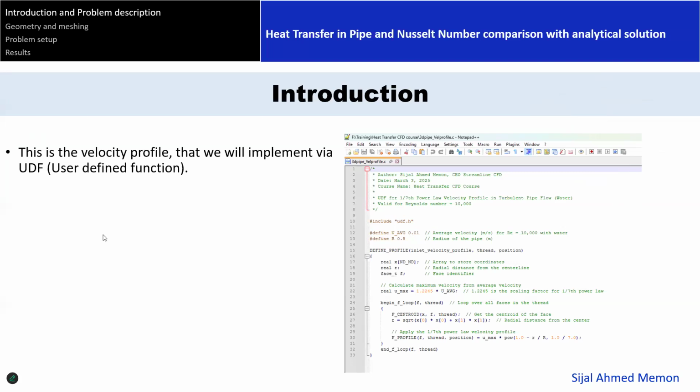For example, if I'm running a simulation on the diffuser, as in wind tunnel testing on the diffuser, what they will provide is some settling chamber ahead of this diffuser. And secondly, they provide treatment on these walls, suction sort of thing, so that no boundary layer is made on the settling chamber walls. So when flow goes into the diffuser, there is a very clean flow. The only variable we are going to monitor is what changes inside the diffuser, not what happens before that.